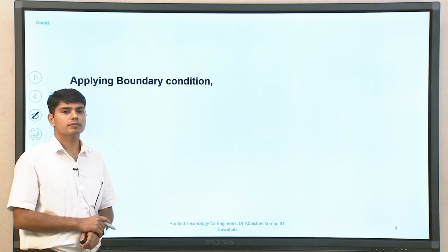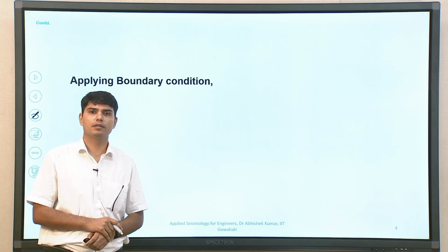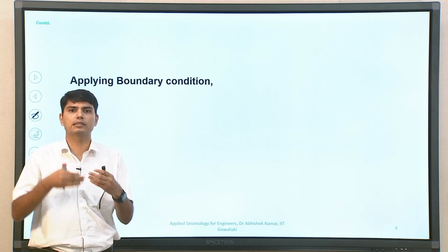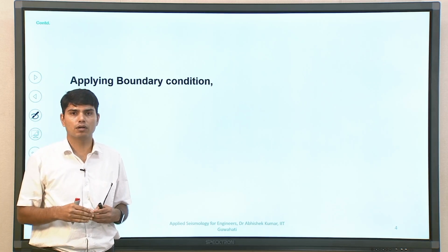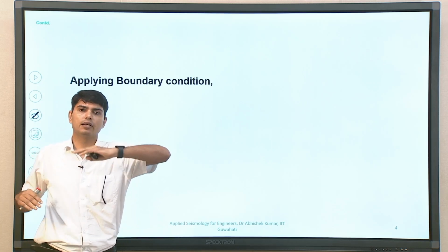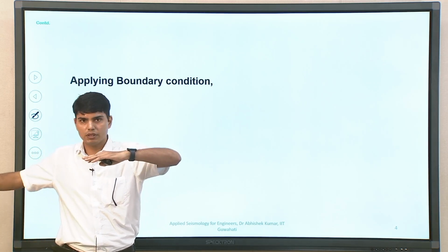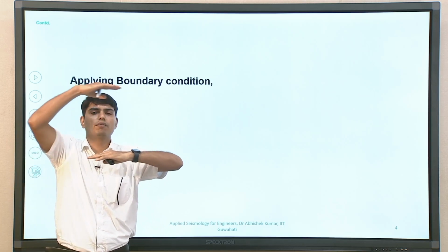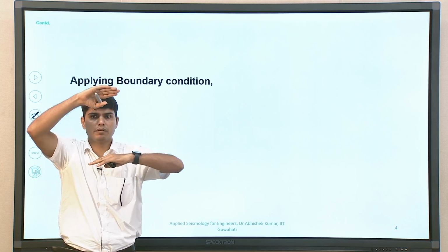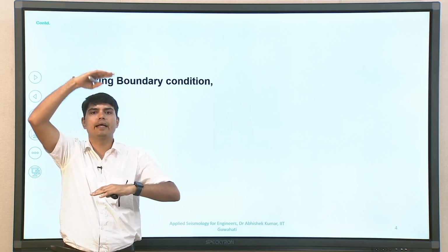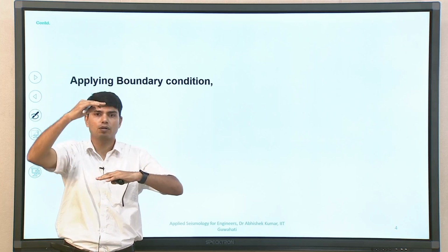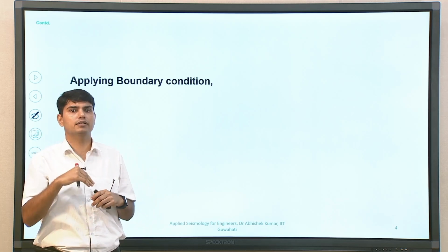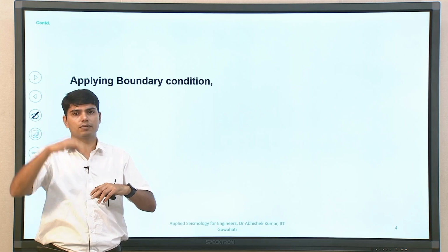Now, again there are some boundary conditions. Remember, in this particular case we are not taking n number of layers above the bedrock. We are only taking into account that there is a rigid bedrock medium on which incident waves are coming, and above this bedrock medium only one layer of undamped soil is available. We are not right now concerned about n number of layers above the bedrock. In practical situations, you often encounter more than one layer between the bedrock and the surface.